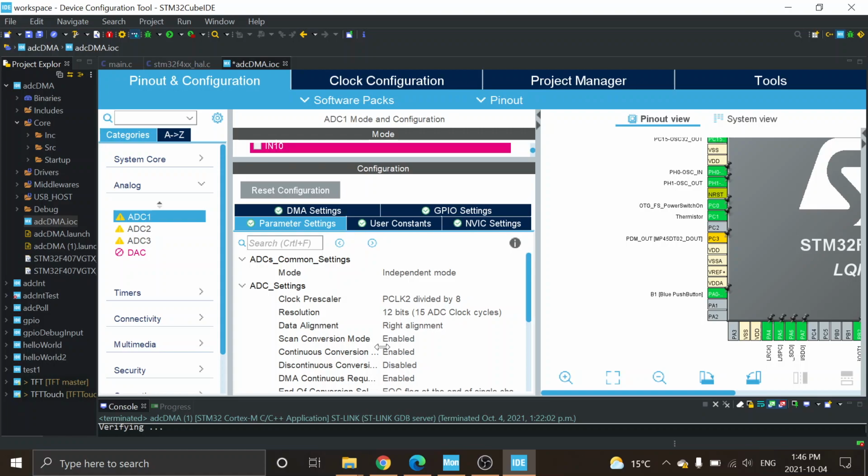And then what I'm going to do in my while 1 loop is go to that memory location and pick out my die temperatures and my thermistor temperatures, add up the 100 values and average them. Okay, and then go and print them out.